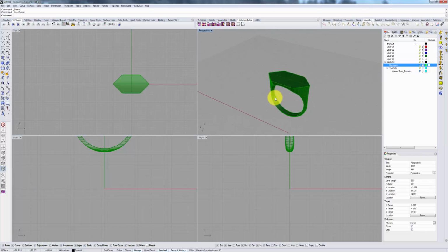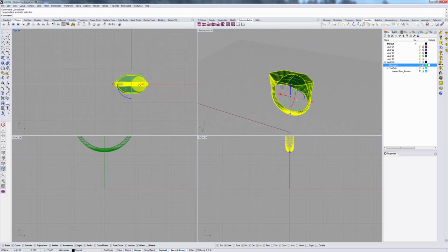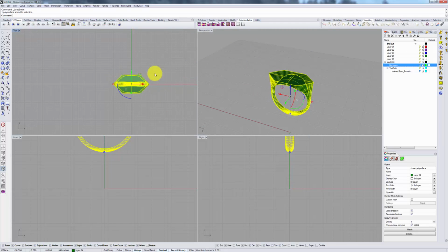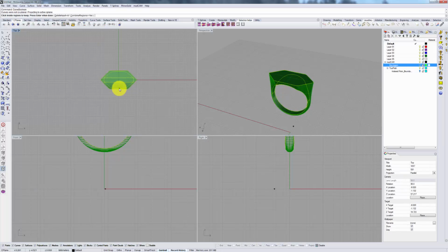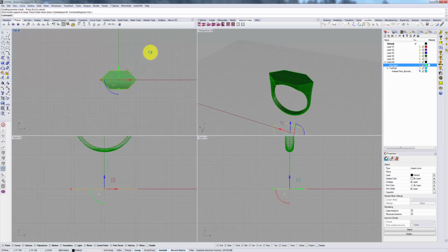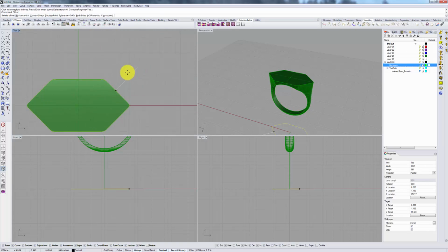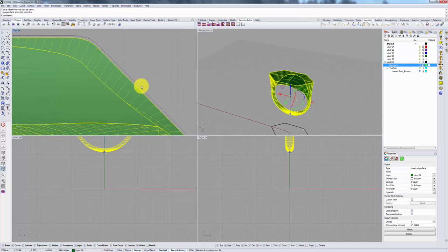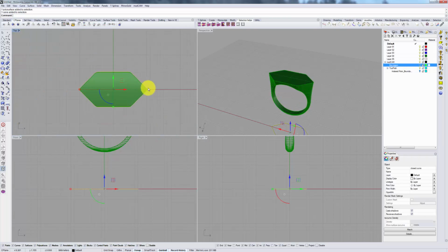First script allows you to create a boundary curve around any object from a given C-plane. To give you a demonstration of this, let's say we have a ring like this, and I want to create a boundary curve for this top part of the ring. I could go through the steps of making a silhouette, performing curve Boolean operation, and then offsetting the curve to reflect my tapered bit by, let's say, 0.1 of a millimeter to get this usable boundary curve.